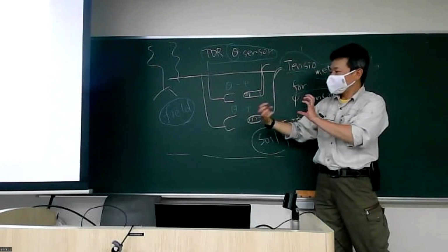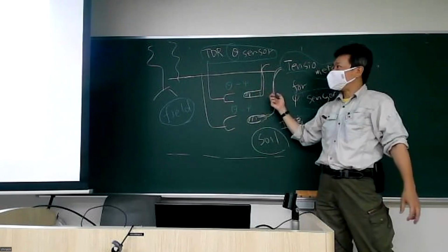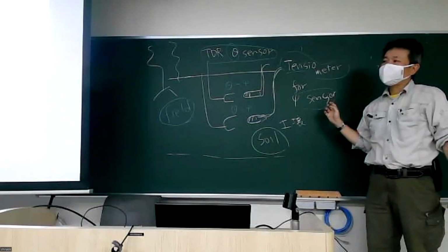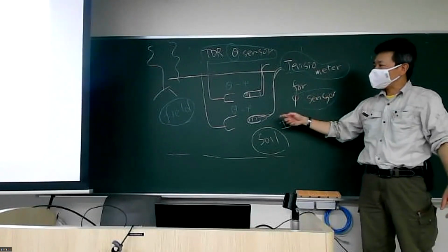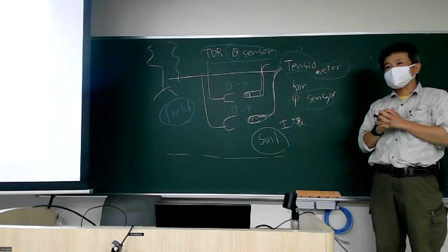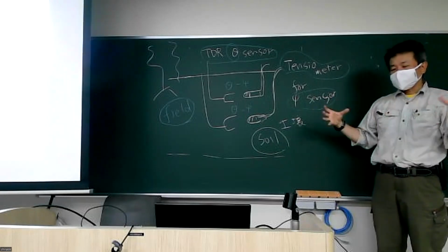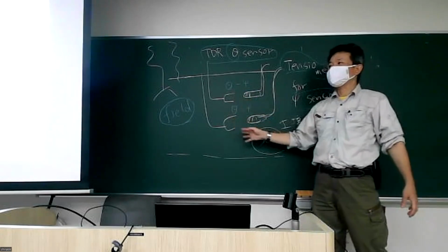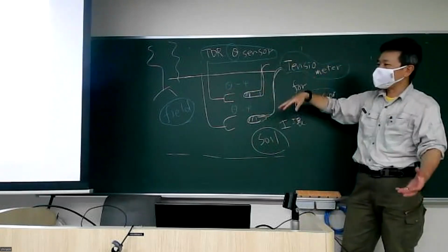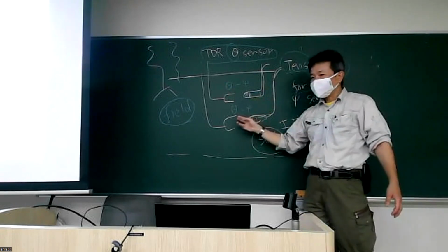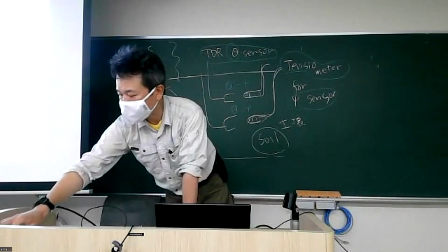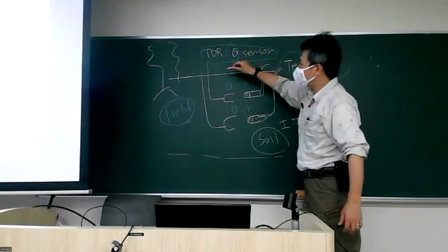We have simultaneous data of theta and psi with this TDR and tensiometer. So this is a kind of check for theta psi at the real field site. This might be the quickest way, and there is no issue of sample size, though burying the sensors is the important part. If we measure theta and psi with TDR and tensiometer during rain, theta psi comes out from the field.